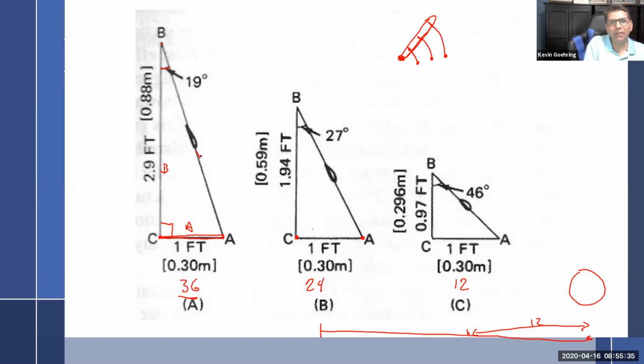And if we kept everything the same, so if we said, well, let's make everything 46, well, then fine. Then this is at 46 and this is at 46. And I could do the math, I'm not going to, and say, whoa, this is the relative wind coming up. That's going to stall. That's going to stall. And we get a little bit of thrust then in this part of the blade. And that's all the thrust I'm going to get is down there at the root, which really has the least amount of thrust anyway, just because it's moving slower and everything else. So that would not work at all.